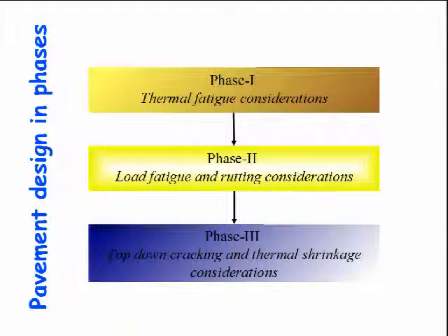It's like what we typically do in beam design in cement concrete design, that we design the thickness of the beam, the depth of the beam, from the bending moment considerations. Additionally, we do a check for the shear and the serviceability in terms of the deflection. So this is a design approach which is suggested.